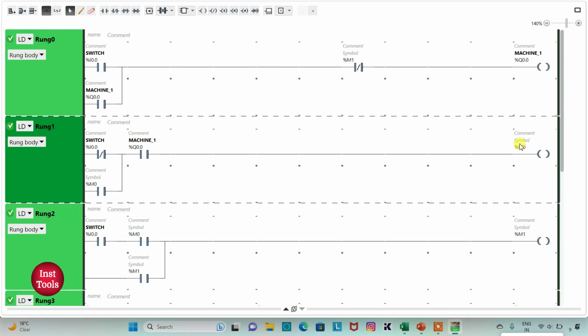So what should it do on a second press? M0 stores data that the switch was already pressed and released and machine 1 is turned on. Then when the switch is pressed and released again, and it has also stored that the switch was once turned on and turned off and machine 1 got on, the current will flow through it and M1 gets activated.